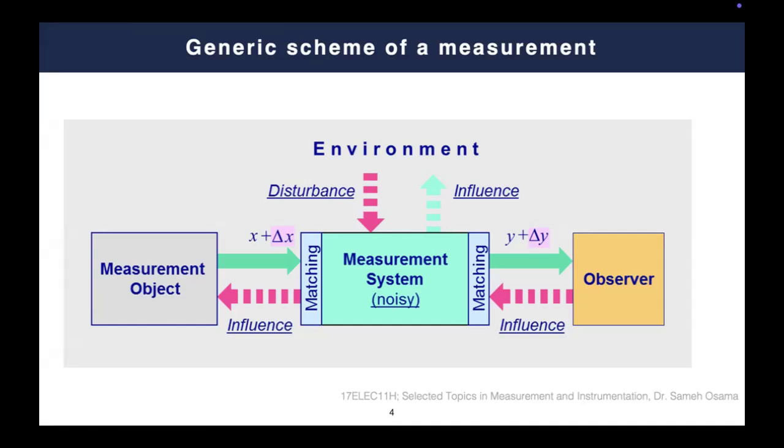So you might destroy the sensor or the measurement system, because simply you selected a wrong sensor, which, for example, can measure a temperature up to, let's say, 200 Celsius. However, your furnace is reaching, for example, 700 Celsius. Definitely your sensor will break down. So herein, the measurement object influences the measurement system. Additionally, on the other side, if your sensor is not well designed, it might impact the measurement object.